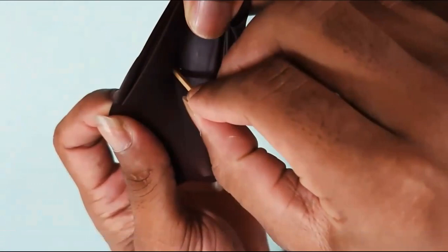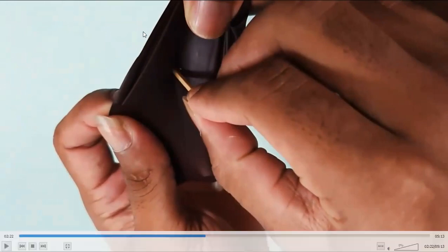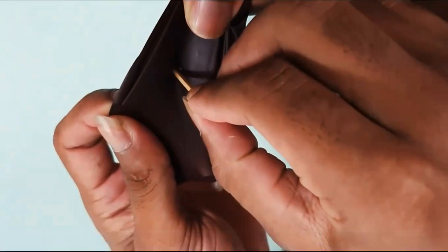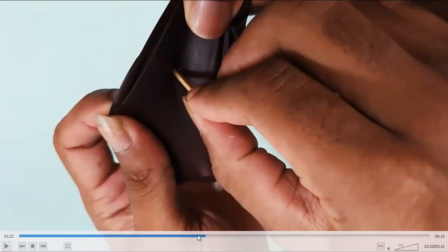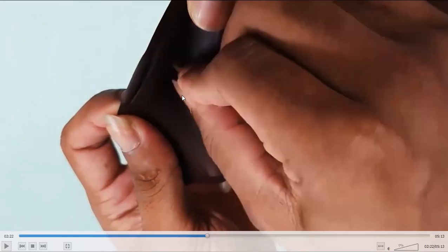It has some stiffness and the ability to resist bending. So this piece of membrane does not have flexural, in other terms, out of plane stiffness. Here we saw the in plane stiffness. It can resist in plane forces, but it cannot resist out of plane forces.